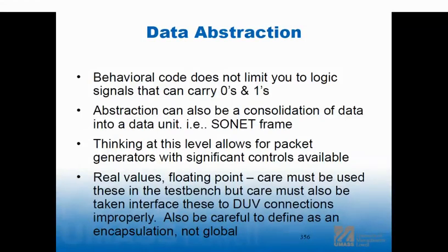If you've taken a computer architecture class, you know it's pretty easy. If you've taken the MIPS class or the RISC-V class, I know when I took that class, I couldn't wait to write the Verilog for it because it wasn't that big of a deal. A RISC processor is pretty easy. It has a register set, but it's well thought out, right? The register set has all the right size things to give you addresses and do math. And then the ALU, you can copy the code right out of the book. And if you don't want to do this, you can just download it.